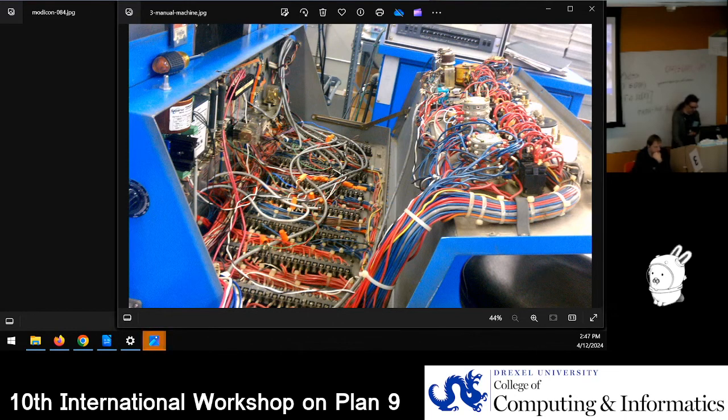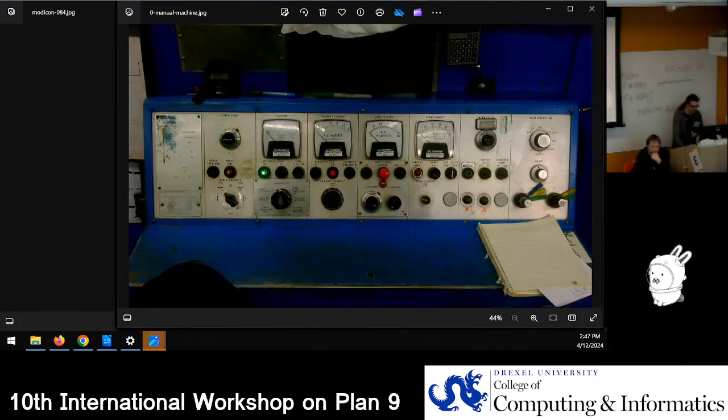This machine right here, this particular panel and everything, is state-of-the-art late 1960s, early 1970s. The person operating this machine pretty much had to know how to operate every single thing. For example, an electron beam welder fires a beam of electrons inside of a vacuum. So the part has to be inside of a chamber, and that's what that is. A little window back there looks into the chamber, and the operator sits in front of it and looks into a little periscope thing.